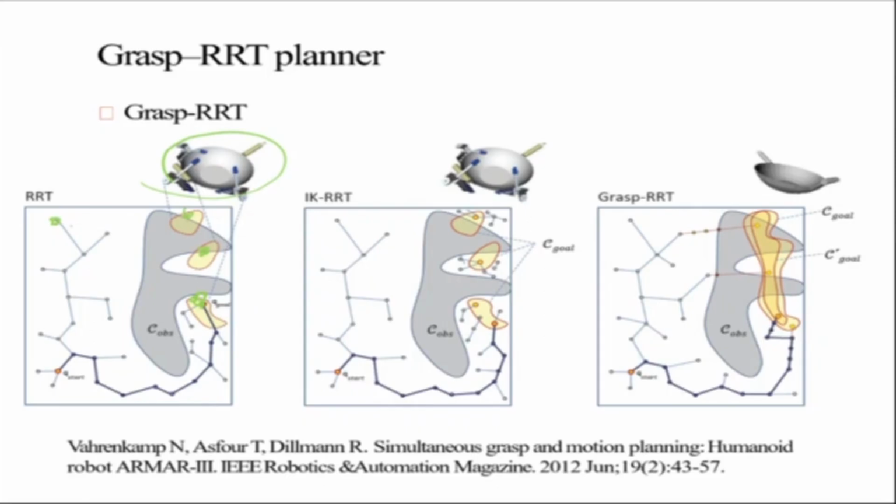What we can do is, by using a sampling based method, I can start from here, start shooting these nodes, make these edges and see, by placing different fingers, how I can go and catch this object and optimize some metric. This is grasping using RRT. But it is extremely difficult because there are 3 fingers. You have to place the 3 fingers such that you satisfy the grasp and also hold the object. But RRT type planners are also used for this kind of task.